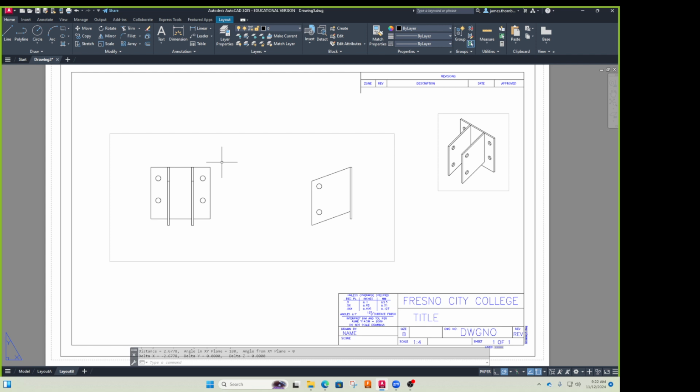And so that's something that changed sometime in the last 5 years. They kind of made that subtle change, so sometimes it can be really confusing. Like I've got this measurement here, I move it a little bit, and then the whole number changes. Because some people, some crazy people, dimension in paper space.